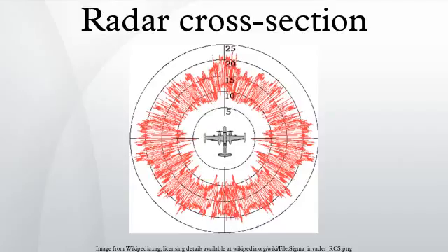The scattering of incident radar power by a radar target is never isotropic, and the RCS is a hypothetical area. In this light, RCS can be viewed simply as a correction factor that makes the radar equation work out right for the experimentally observed ratio of received to transmitted power. However, RCS is an extremely valuable concept because it is a property of the target alone and may be measured or calculated. Thus, RCS allows the performance of a radar system with a given target to be analyzed independent of the radar and engagement parameters.